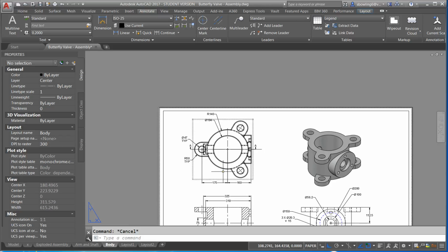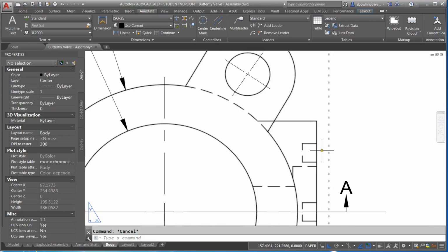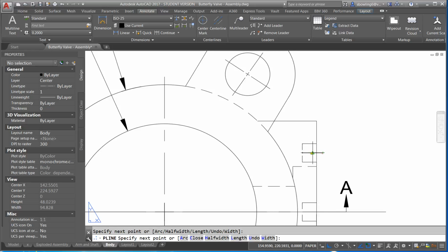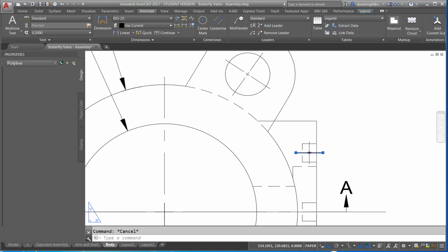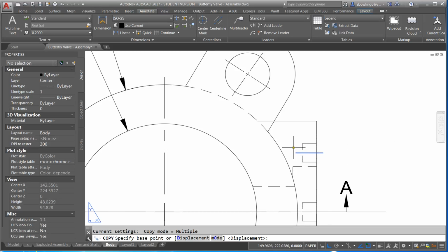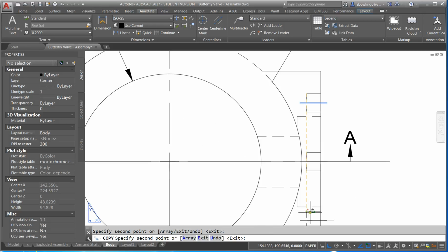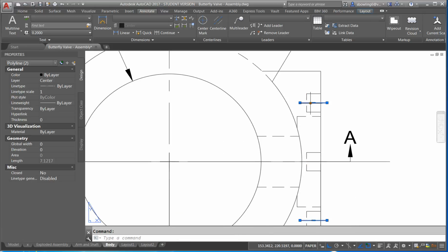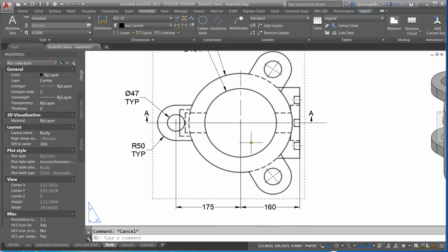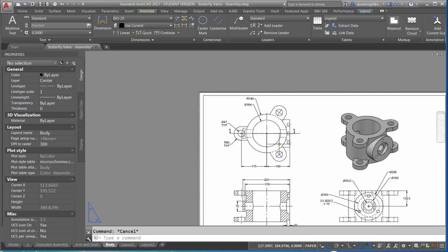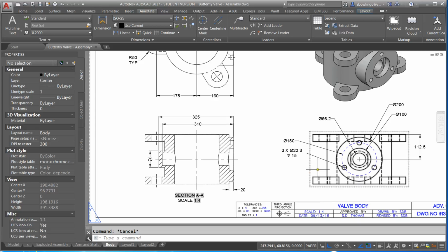Okay. So you also have polylines that are to the midpoint here. Copy those. And sometimes the lines will just be too short to be hidden like that. And sometimes you may end up just having to change the LTS scale or the line scale over here. But again, I don't recommend doing it this way for major drawings, just for the fact that when you're designing, you don't want to do that.